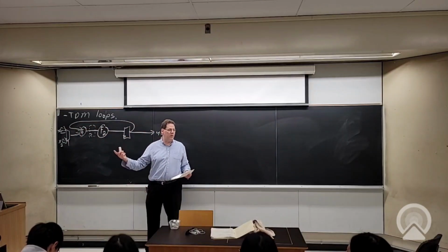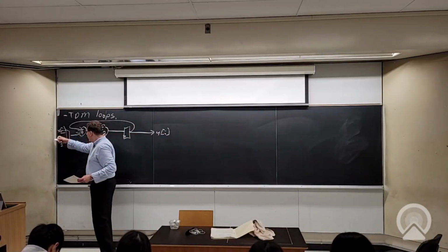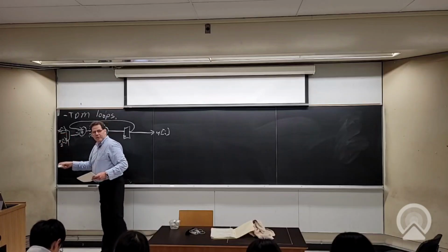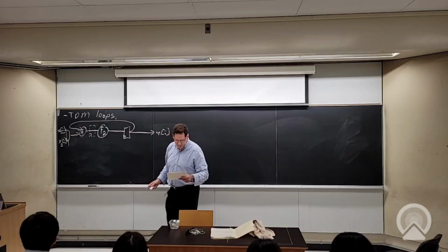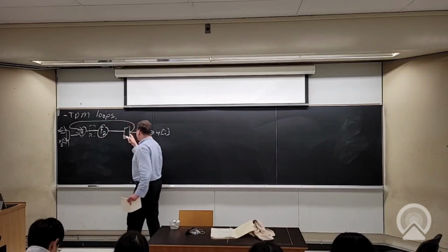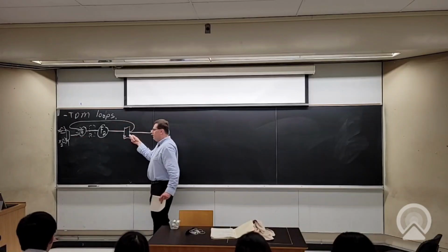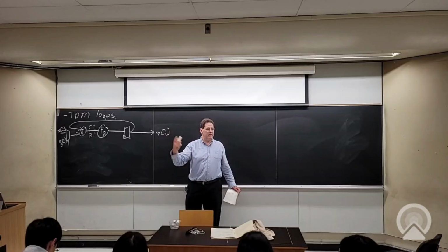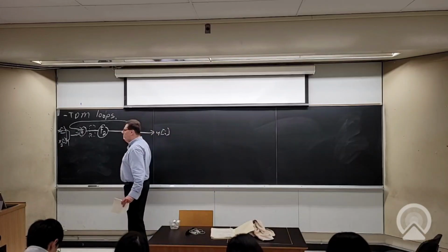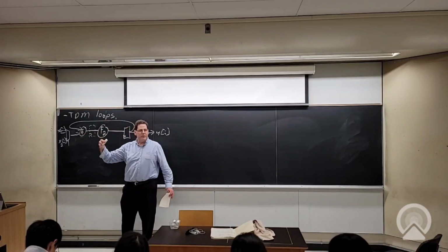I'm going to take cycle 0, I'm going to take something from x1. Cycle 1, I'm going to take something from x2. Cycle 2, I'll go back to x1, and so on. So I'm going to ping pong back and forth between my two streams. Okay, so what does that do? It means that from the point of view of one stream, my output is still a function of the current input and the output value one cycle ago, like the previous output value for that stream. That's actually 2 clocks ago, but because I'm interleaving two streams, it is only one value earlier in my stream.